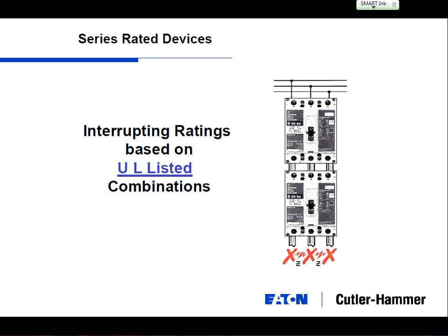For hospitals or critical operations facilities, this is mandated by code, not for all of the distribution of a hospital, but for anything that is considered life safety, critical, essential equipment. And when selective coordination comes into play, you cannot use series rating whatsoever. In series rating, I've got two breakers, they're tested, and something will trip, but I can't tell you which one will trip. I'm just telling you something will trip and take it offline. In selective coordination, I'm telling you this one will always trip first ahead of the upstream device.